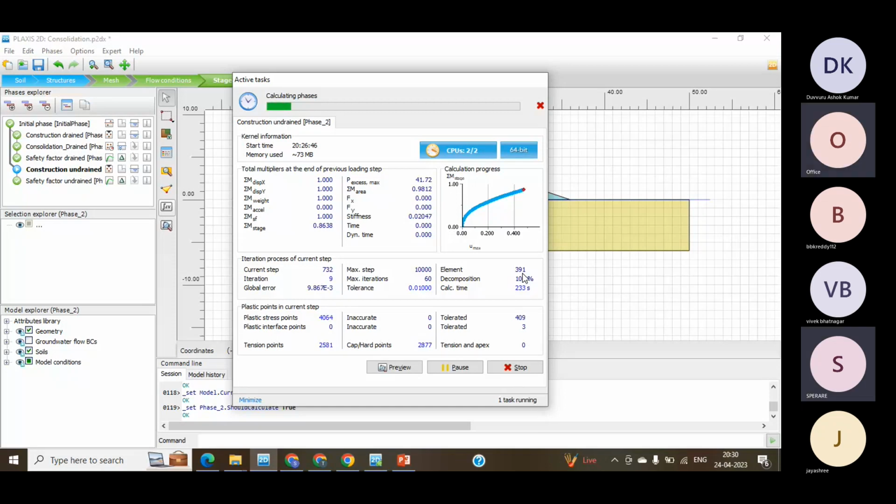So the main idea is, when you end up with a warning that says there are not enough number of steps, then what you have to do is come back here and look into that particular error, and the error code is always 102.